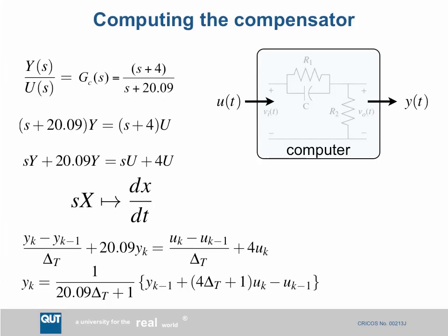So we've talked a bit about how we can compute a compensator. You've learned previously about how you can design a compensator for a plant using networks of resistors and capacitors. You design it in the S-plane, you implement it with op-amps, resistors, capacitors, or other sorts of discrete electronic components. But it's just a function, and we've talked about how we might be able to compute that.